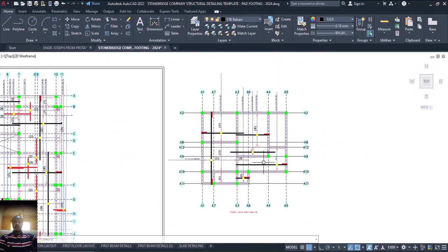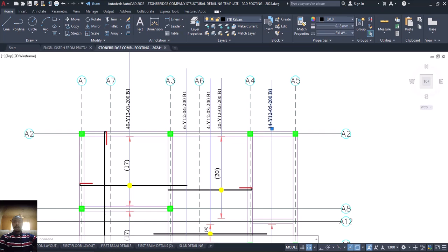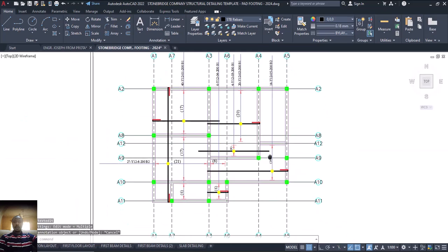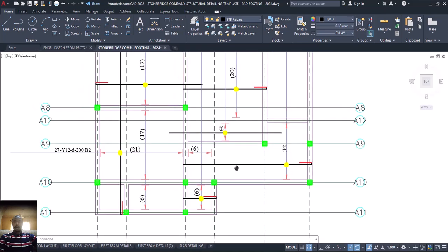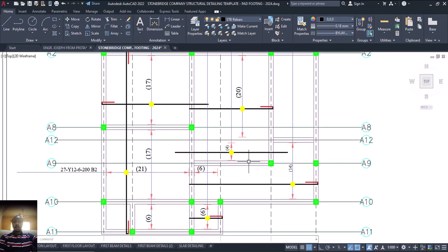So now from what I've explained, I can now decide to make this one B2. Is that okay? I can now make this one B2. Delete this and make this one B2. Is that okay? This one B2. Why? Because if you look at this, this is a one-way slab. Is that okay? Here, the dimension here is a one-way slab. It can be 2. So that is that. So my one way on this particular aspect now will now be along this line.